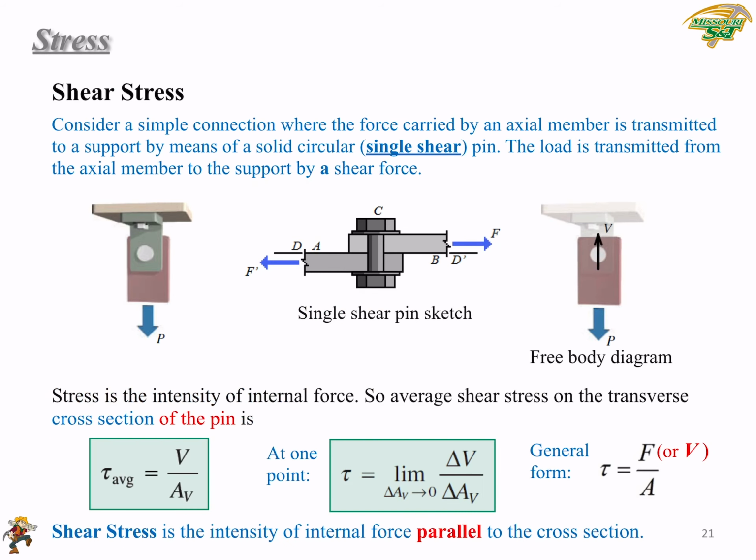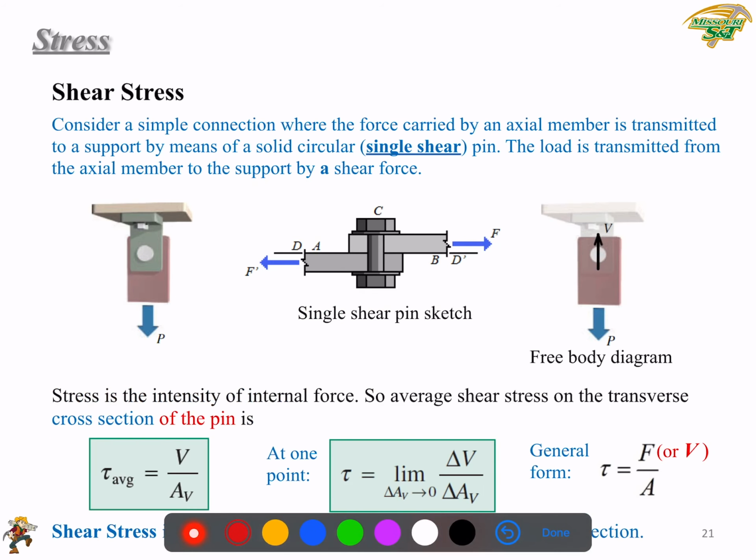And here is the only cross-section, the only one cross-section carrying the shear force. Okay, so that is why we call it a single shear pin. Okay, you can only find one cross-section that carries the shear. Okay, the free body diagram is shown here.